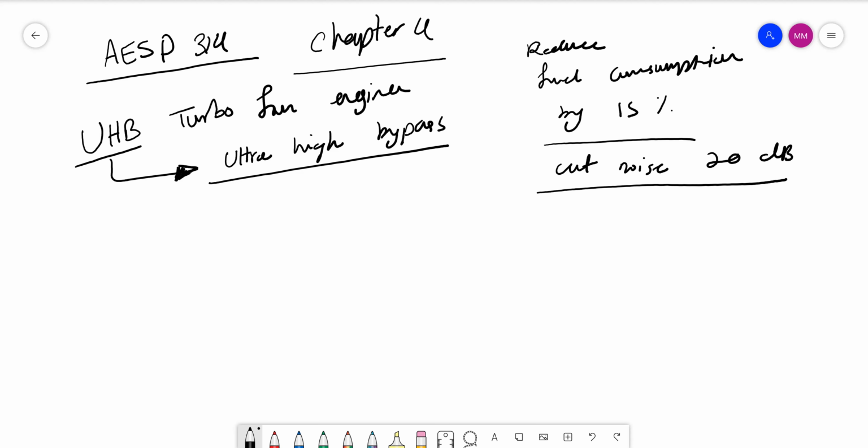The bypass ratio here is getting very close to turboprops, which is going to be the topic from next week, right? So the bypass ratios that you're gonna see in these type of engines, it ranges from 10 to 35 to even higher, like 60, 70.